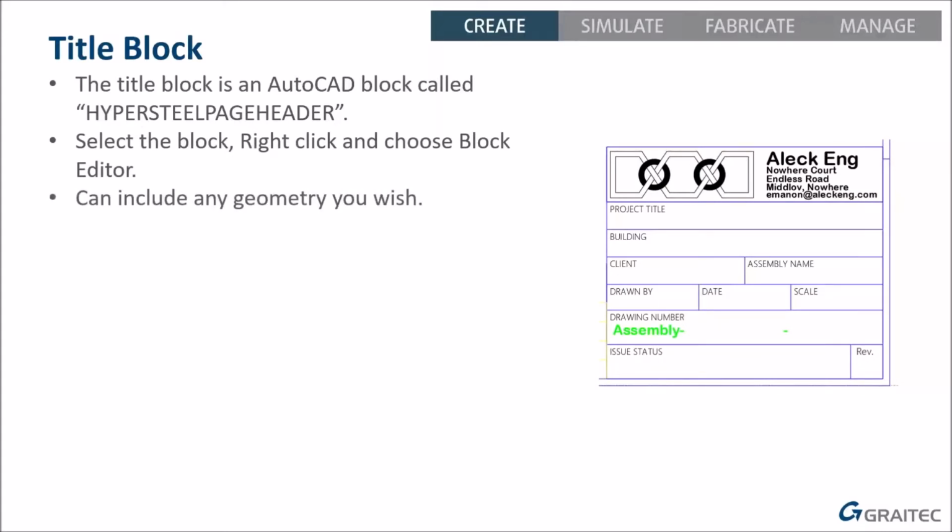And then once again, you can include any geometry you wish, so you can draw any circles, draw any shaped boxes and bits and pieces in there. I've made this one taller and narrower instead of wide and flat. But again, the overall shape should be a rectangle. If I had some extra notes sticking out here, it's not ideal to have different heights, because again, Advanced Steel will treat it like it's a rectangle, the smallest rectangle that can include everything within the block. So you might as well fill up that rectangle and lay things out in a nice rectangle rather than having different levels of different bits.